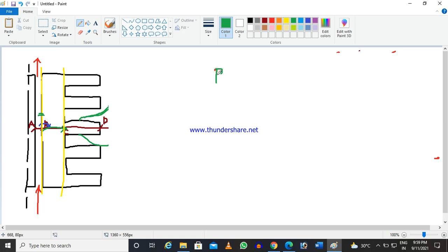So that is your resistance, say R1. Then it is flowing through the solid, so that is R2. Again from here it is solid to air, that is R3. So this is your overall thermal resistance. This is to be estimated.